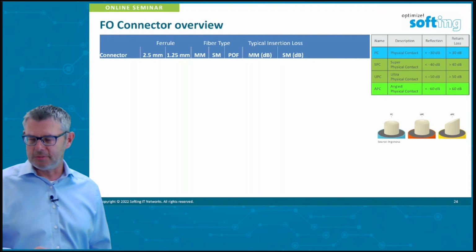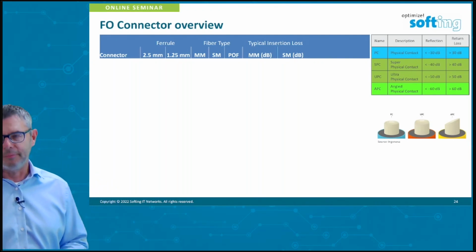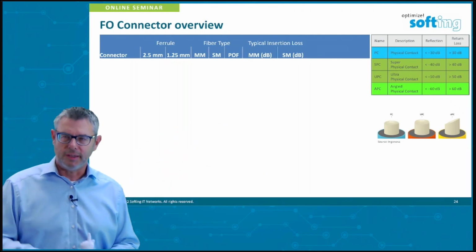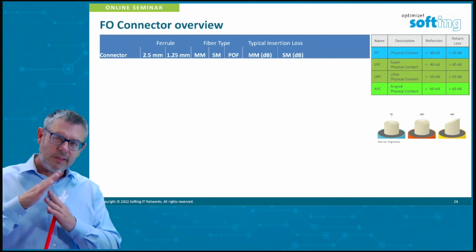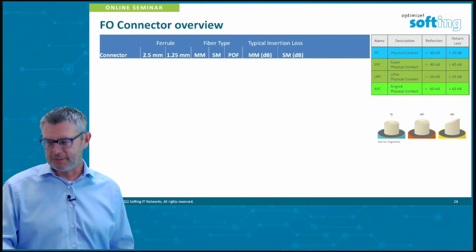For long distances, we have a typical cut shape. This is APC, angled physical contact, and you see the connector on the very end with an angled tip, which is 8 degrees. This has a couple of advantages for single mode transmission over long distances.